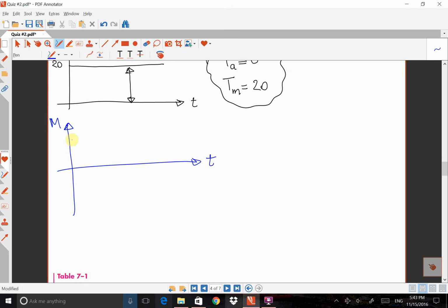At this time, the moment is at maximum value, which is 16.36. But when the shaft is rotating, at point B, the amount of moment will decrease and come to 0. And again, when we rotate, it goes to some negative value. And that negative one is exactly the same. And then again, it's going to increase, go to 0, and then go to maximum, and come back, and continues like this.